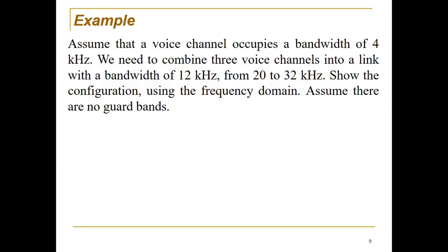or between two users or two services. Like for instance, with some radio stations, if you notice, the channel after a given channel has some gaps in between. If you take Joy FM 99.9, the next one will probably not be 100 something. There's always some gap, maybe at 101 point something. So the gap between 99.9 and 101 forms the guard band, designed to avoid interference between two frequency channels allocated to given transmissions.